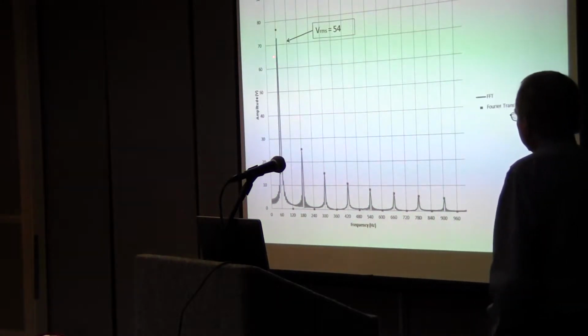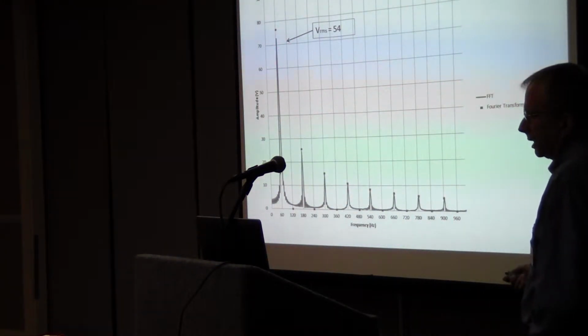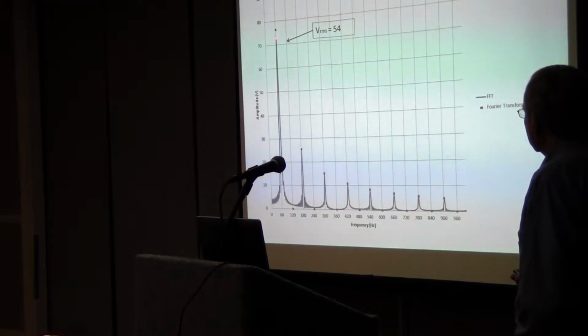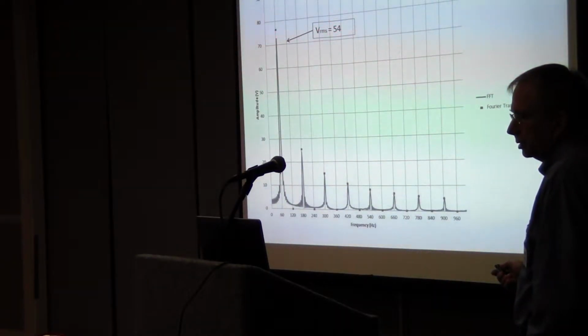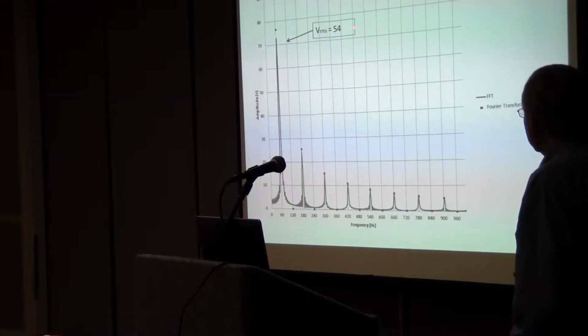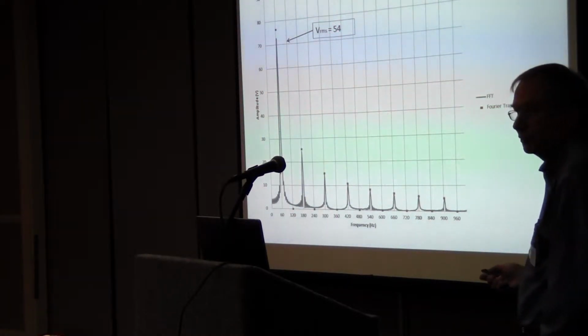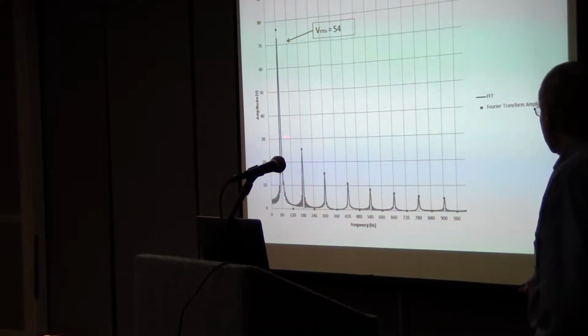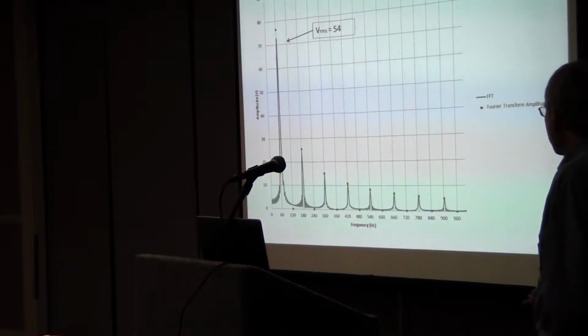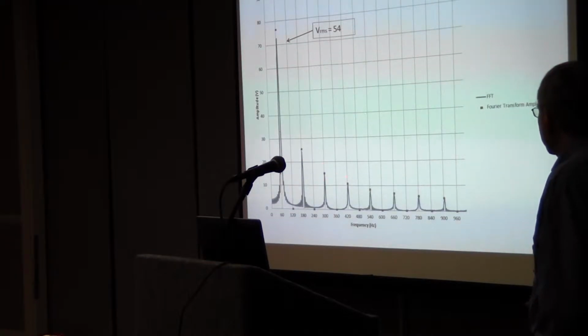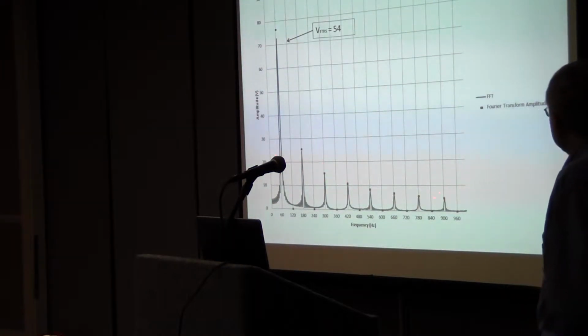is. If you do the frequency response of that square wave, you find that, lo and behold, there is a component at 60 hertz, but it's only the equivalent of 54 volts RMS. So a 120 volt square wave produces 54 volts RMS of 60 hertz, and then a decaying group of harmonics that are multiples of the 60 hertz. And they're odd harmonics, so 180, 300, 420, and so on, that decays off.